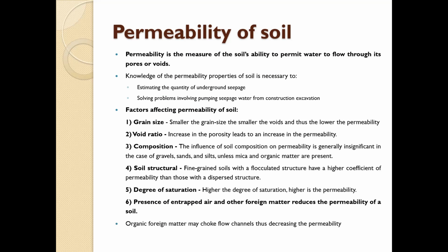So to begin with, the permeability of soil. Permeability is the measure of the soil's ability to permit water to flow through its pores or voids. You have learned this in soil mechanics or geotechnical engineering. The knowledge of the permeability properties of the soil is necessary, first, for estimating the quantity of underground seepage, and second, for solving problems involving pumping seepage water from construction excavations. So for these things we need the knowledge of permeability.